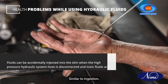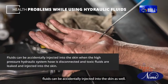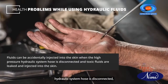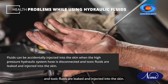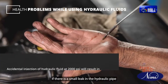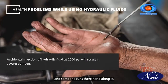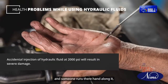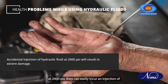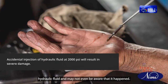Similar to ingestion, fluids can be accidentally injected into the skin as well. This takes place when the high-pressure hydraulic system hose is disconnected and toxic fluids are leaked and injected into the skin. If there is a small leak in the hydraulic pipe and someone runs their hand along it at 2000 psi, they can easily incur an injection of hydraulic fluid and may not even be aware that it happened.